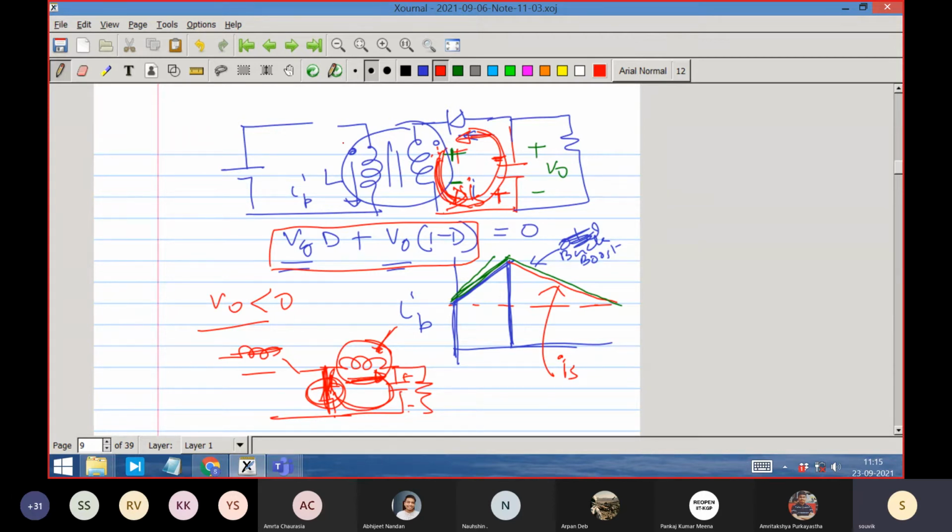This voltage is so, and effectively that is what you are saying, because after conduction, what is the voltage across the inductor? Voltage is equal to the capacitor voltage plus the diode drop. So that much voltage will develop across this inductor coil, and it will clamp it, because it cannot change the capacitor voltage, and this energy has to be continuous, this current has to be continuous.